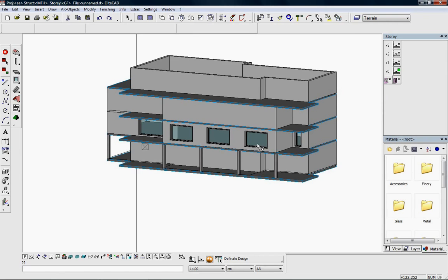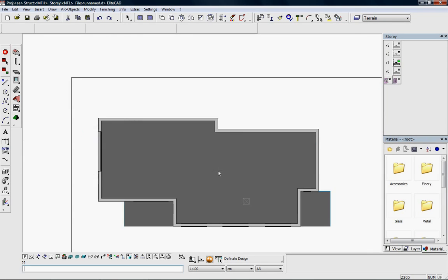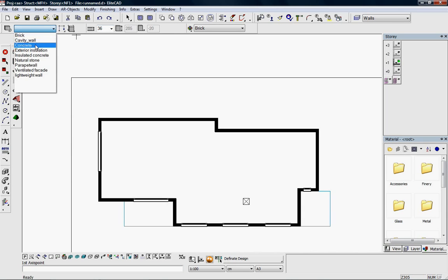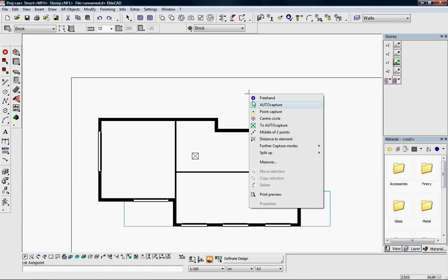Now we can extend the floor plan with the walls. We select a brick wall from here to place it directly into the plan. Here we have the possibility to add desired wall sections into the building. The walls naturally fit well with the outer walls so that we have clean edges and intersections. We also have the possibility to extend walls in this way.